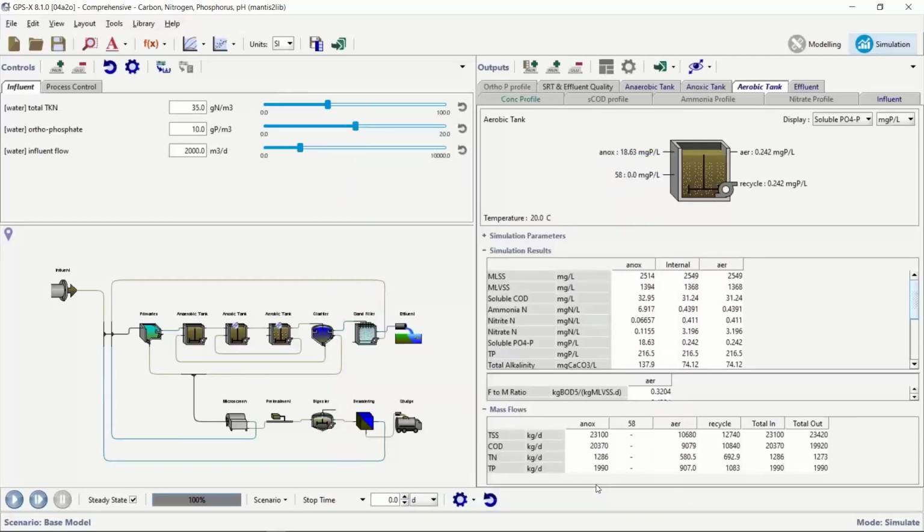So sometimes when I'm working on these types of somewhat complicated activated sludge systems, especially when you got 2, 3, or 4 or 5 different kinds of biomass going on, and you really want to dig in and understand, maybe I can see a concentration coming in and a concentration going out, but it's not telling me the whole story. Going to that Mantis 2 rates menu is really useful, even if you don't know the absolute number that you need, but you can see relative to other rates, which is the most important thing happening in that particular unit. Okay, so that tells me mostly what I wanted to see.